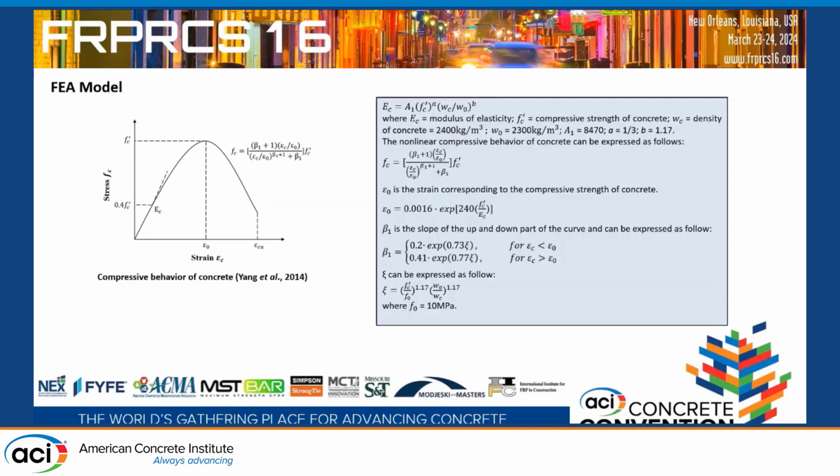For this model, we just need to know the compressive strength of the concrete, and then we can use all these equations to calculate every point on this curve. We can get the elastic stage and the plastic stage, and then we just need to enter all the data into ABAQUS, and we can simulate the compressive behavior of concrete.